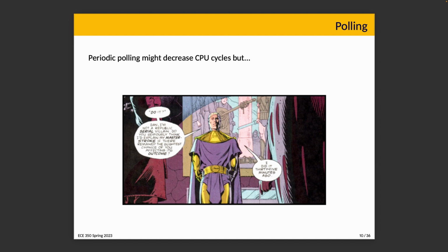If the storage for the device is very limited, and the data that's currently ready is not retrieved fast enough, then it's possible the data that's there gets overwritten by the next chunk of data before we get a chance to get to it. So, even though we don't always like tight polling, sometimes it might be the best way to ensure that we don't miss any data.